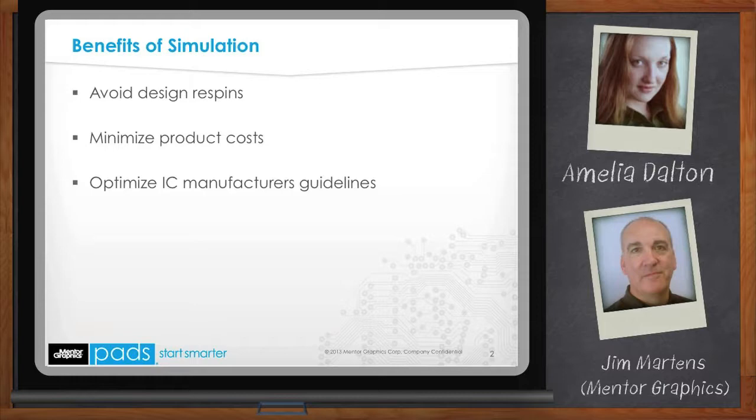Sure. Through simulation, you can identify which circuitry dominates your system, allowing you to focus your efforts on reaching and maintaining signal integrity in your critical areas more quickly. Yeah. For each stage of the design process, there are simulation analysis tools that can help you choose the best parameters for your board, define necessary constraints, select the optimal set of components, and ensure effective placement and routing. These tools are in areas of signal integrity, power integrity, analog, thermal analysis, and 3D simulation and analysis. Yeah, okay. So simulation is great.